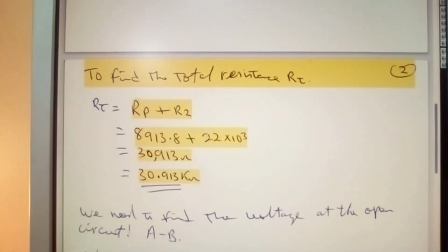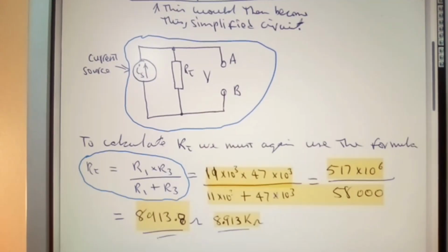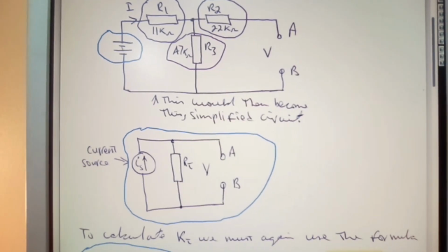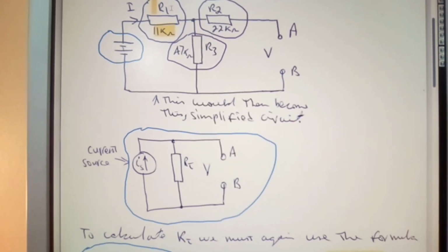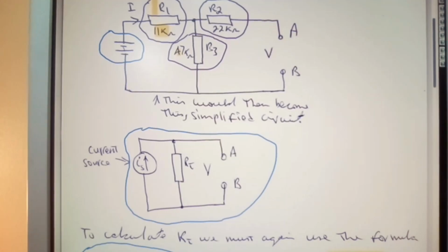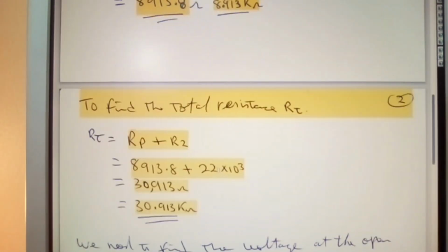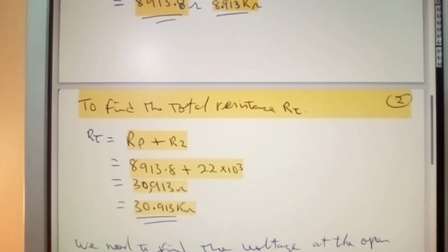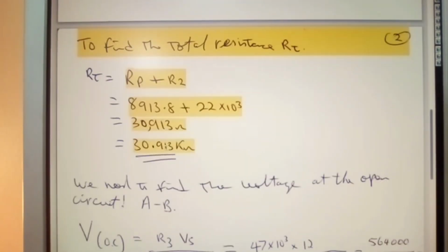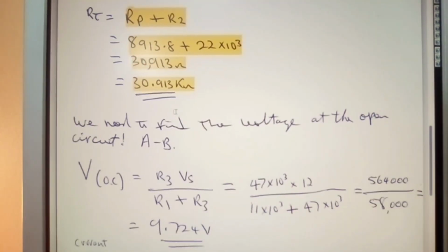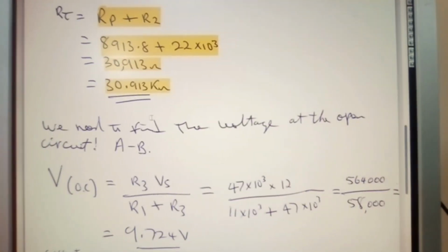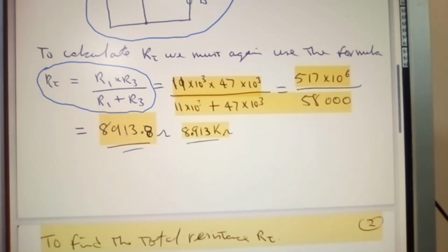And that's all I've said here. I'm just showing you what I did to get the total value, because we did these two here. Let me just highlight like that. We did just these two. And all I'm now saying is that we now have the resistance in parallel plus the value of R2, and that's what we have here, giving us the total value of this circuit in regards to its resistance. So this is not the final element here. Let me get back to my pen.